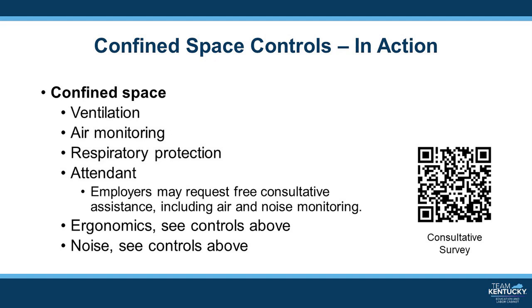The air quality in a confined space is critical. You must start with evaluating the air and other hazards before going in. Depending on the situation, you might need to conduct air monitoring during the welding process inside the confined space. Gases such as helium, argon, and carbon dioxide displace oxygen in the air and can lead to suffocation. Particularly when welding in confined or enclosed spaces, carbon monoxide can form. This poses a serious asphyxiation hazard.